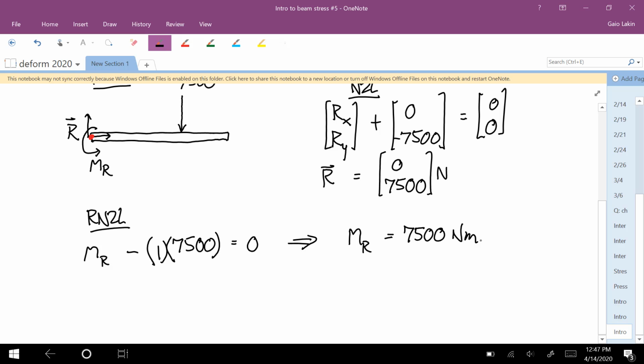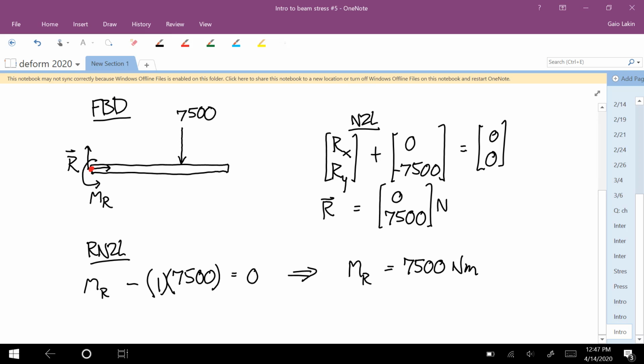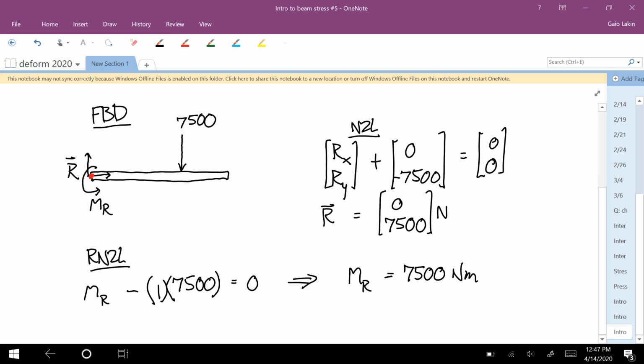And one thing you have to be careful about with the cuts is if you look at this free body diagram of the whole thing where we've already used the equivalent load, that point force representation of the distributed load, it looks like we're going to have 2 cuts because we have this point force 1 meter from the left. But that's not really what we have.